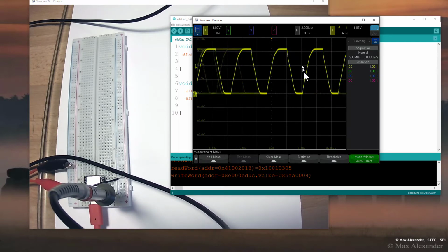Now you see the little ghosting images here. That's because of the timing that's involved here. The Xiao module is constantly checking for interrupts. We can turn them off locally as needed, but if we turn them off and we leave the program while they're off, that will brick the module, and I'll demonstrate that in one of the next videos. But for now, just ignore that ghosting. That just says that, okay, we're not getting perfectly reproducible timing. We'll have to control timing within a loop if we are concerned about accurate timing.